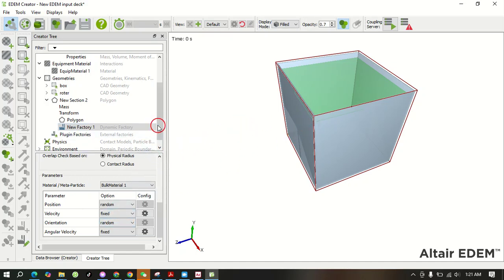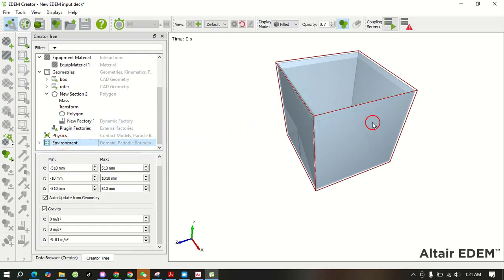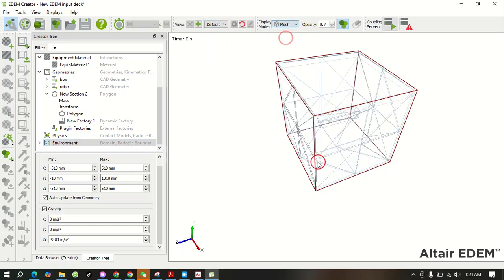This is okay. The next thing is environment. Here we can see that the gravitational force should be in the minus y direction. So from here we can check the mesh, it must be in the downward direction. But in this case it's in the z direction, so we will copy this one, cut this, and here we will put the value 0, and we will put the value here. Now it's in the negative y direction. So our model is almost ready.